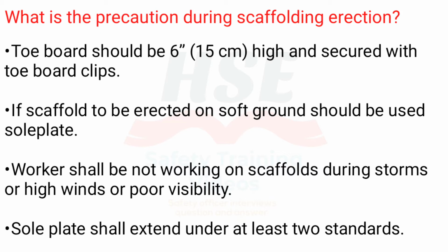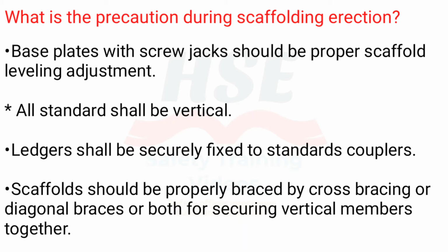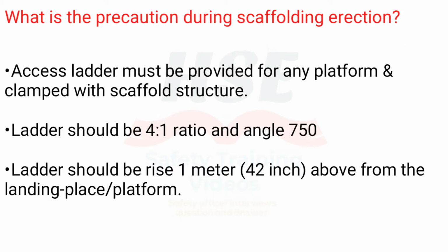Sole plate shall extend under at least 2 standards. Base plates with screw jacks should be used for proper scaffold leveling adjustment. All standards shall be vertical. Ledgers shall be securely fixed to standards with couplers. Scaffolds should be properly braced by cross-bracing or diagonal braces or both, for securing vertical members together.